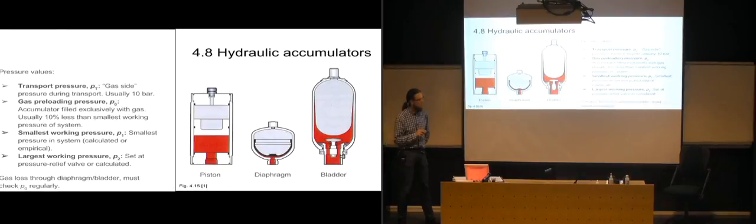And you will have gas loss both through the diaphragm and through the bladder. You can actually have gas loss in the piston also, past the seal there. So that is also a possibility. It's going to be very small, but it is a possibility that it's going to happen. It will be small enough that most likely your filters or your tank is going to dissipate it. So you won't really notice it in your system. You're not going to get large bubbles in your system or anything.